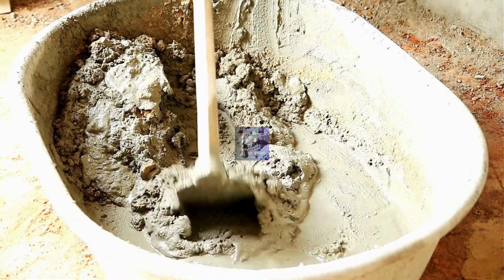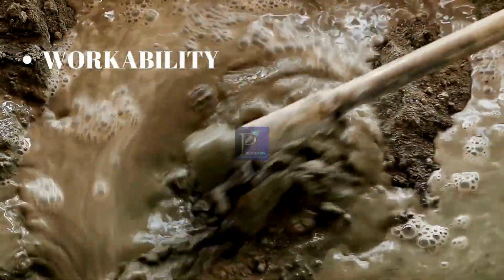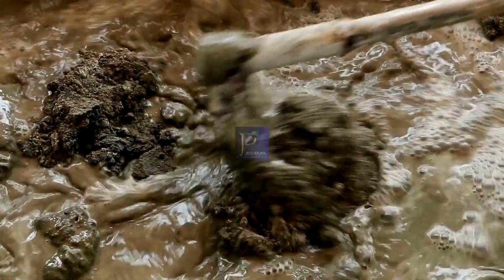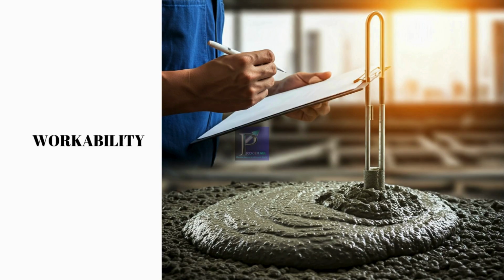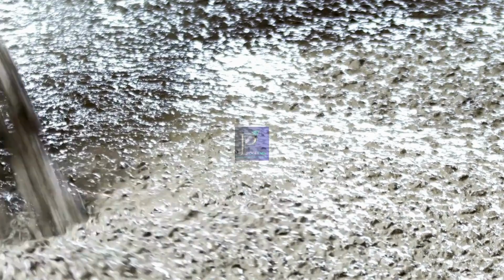Then, workability. Each batch of concrete shall be tested for consistency immediately after mixing by one of the methods described in IS 1199-1959, provided that care is taken to ensure that no water or other material is lost. The concrete used for the consistency test may be remixed with the remainder of the batch before making the test specimens.